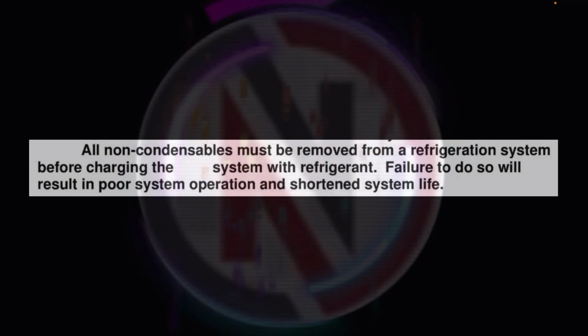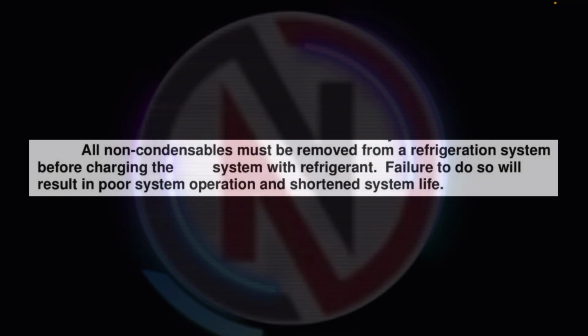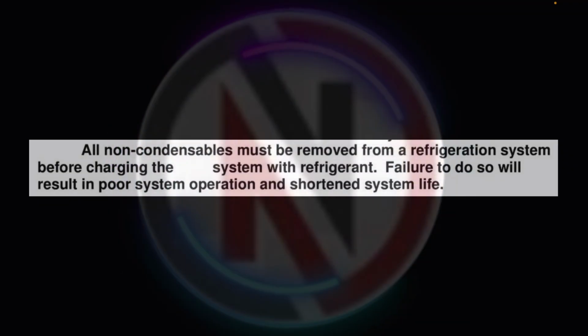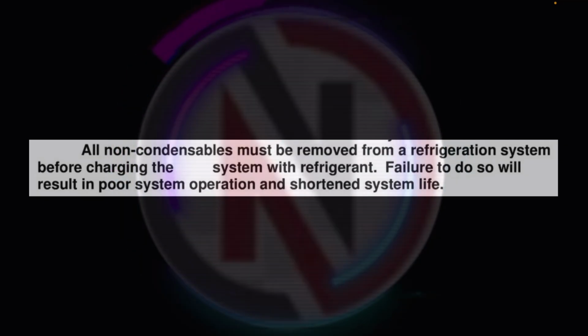All non-condensables must be removed from a refrigeration system before charging the system with refrigerant. Failure to do so will result in poor system operation and shortened system life.